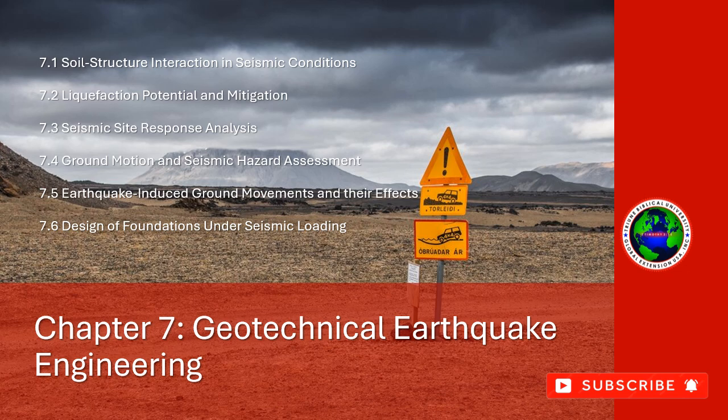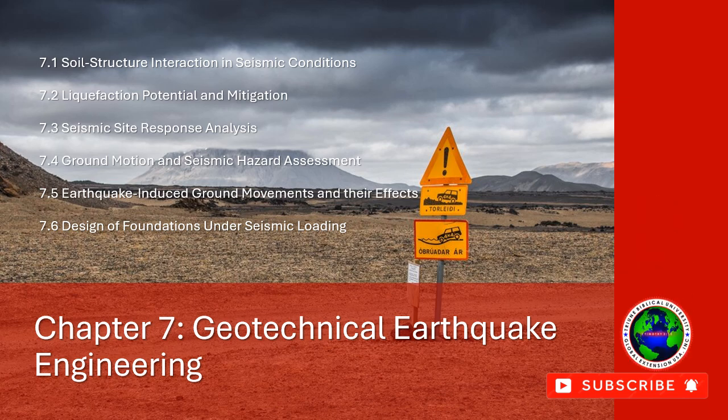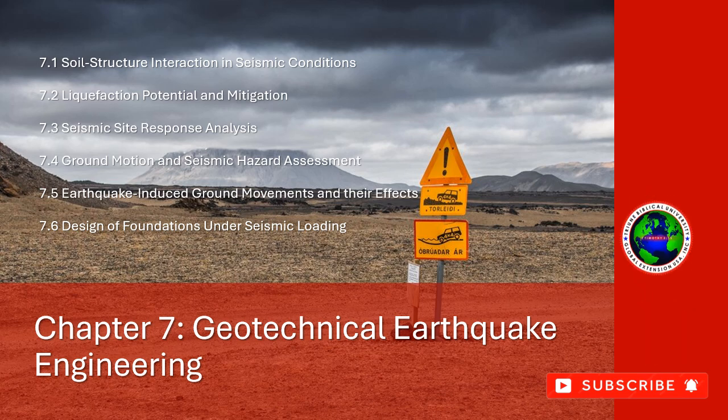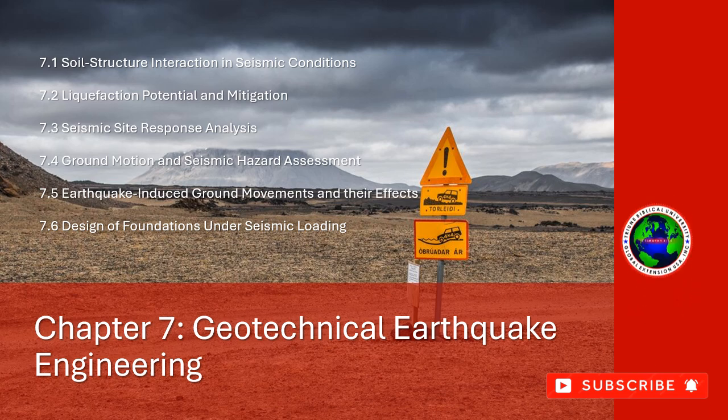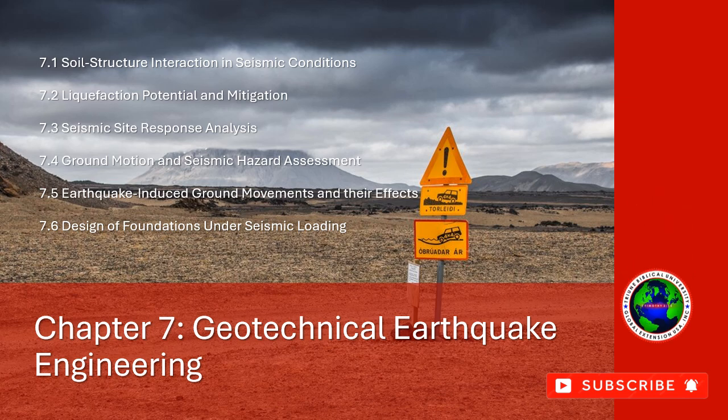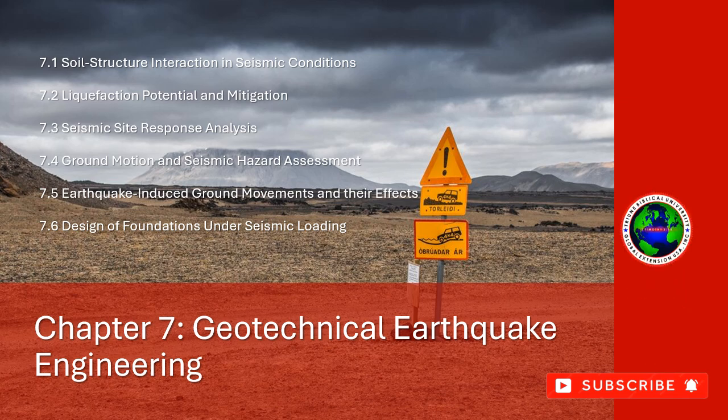Earthquakes can trigger landslides and slope failures, particularly in areas with steep terrain or loose, unconsolidated materials. Seismic shaking can cause the soil on slopes to lose its stability, leading to landslides that displace large amounts of soil and rock. Landslides can result in property damage, road closures, and significant disruption to infrastructure. 7. Soil amplification.